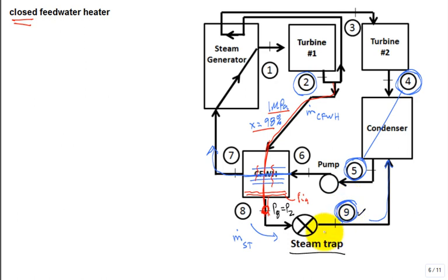It's a low pressure. And now you've done it all. You've done all the work, okay? You've got the pressure here and you've got the pressure there. The pressure at 8 is 1 MPa. It's an intermediate pressure. The pressure at 9, 20 kPa, low pressure. What has to happen?